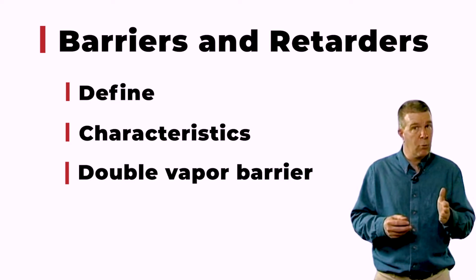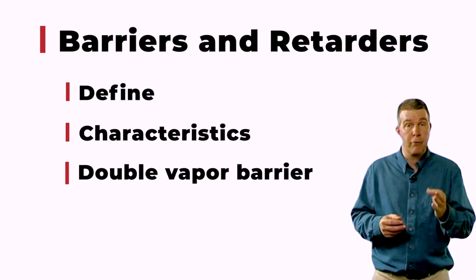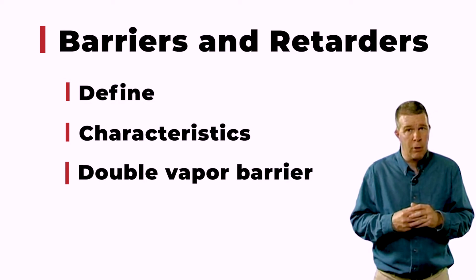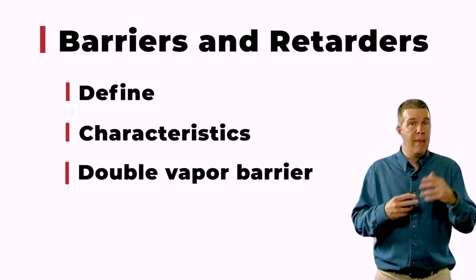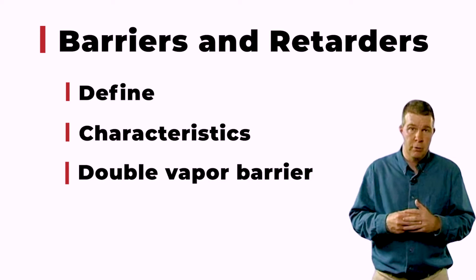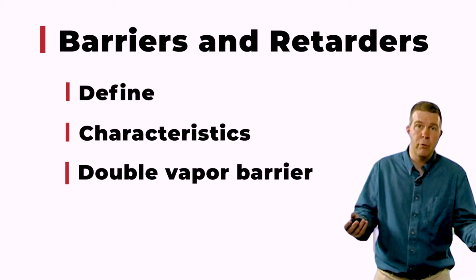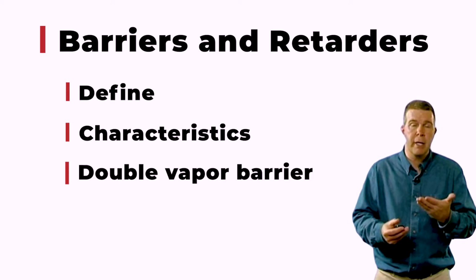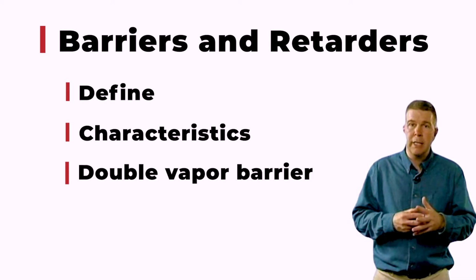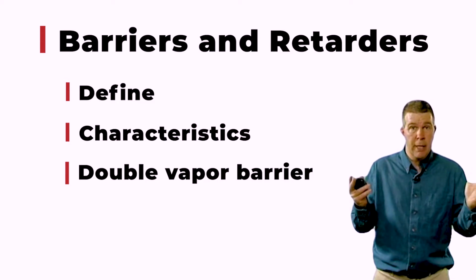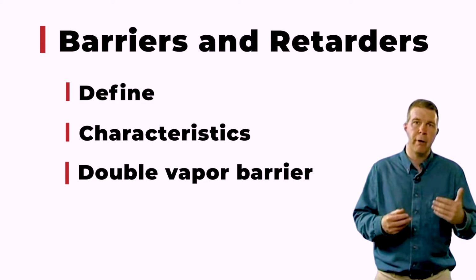But the last thing you ever want to do is do it on both sides. For instance, if you're putting a roof panel package up, you certainly don't want to put a SIP tape on the underside of the panel and then put an ice and water shield continuous membrane roof on the top side. You've created a double barrier. If water leaks in there, and my rule is it'll always leak in somewhere somehow, it can't get out because you've put a barrier on both sides.